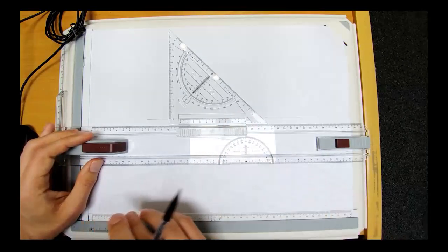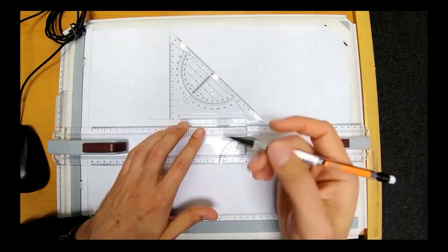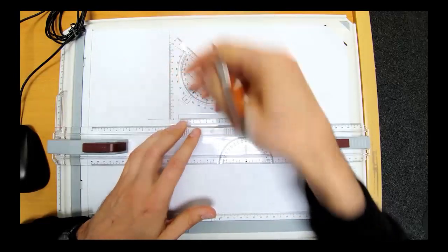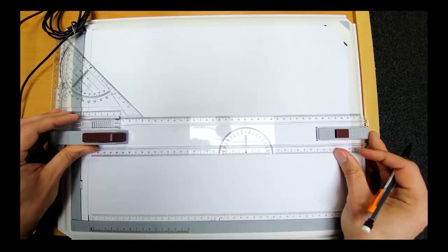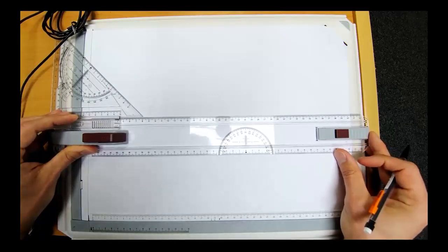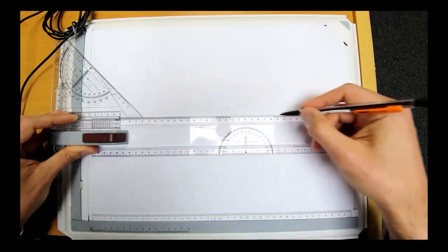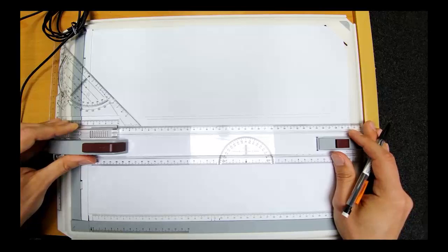So doing the conversion, dividing by 50, it's 3.4 millimeters on paper. So 3.4 is something around here. You just mark it there and draw the second line for this wall. Again, very thin and light lines. So you can see there.